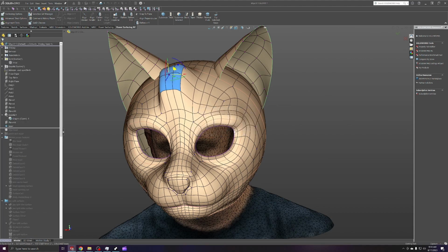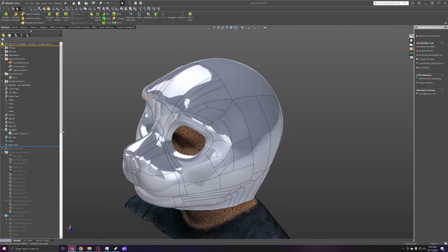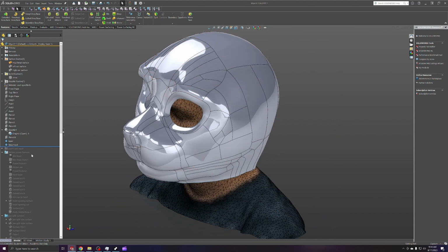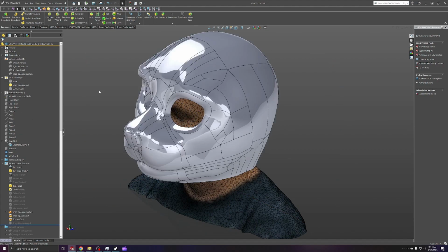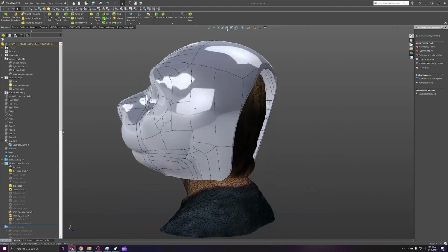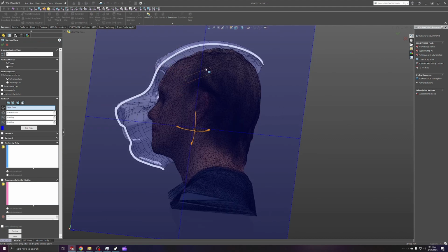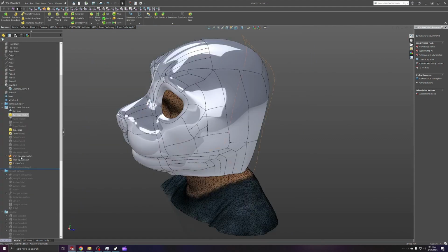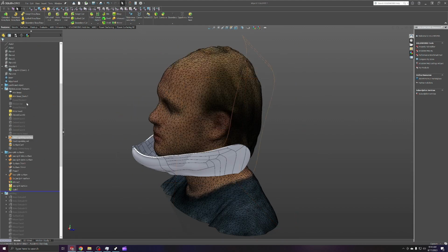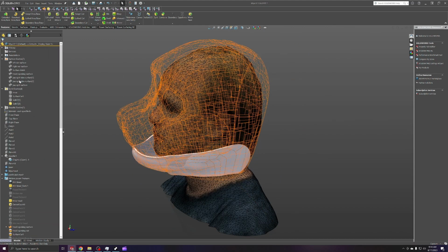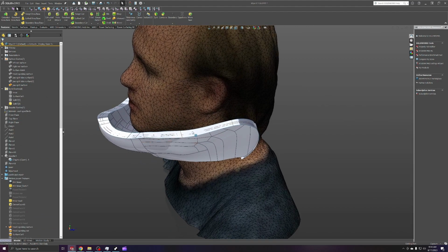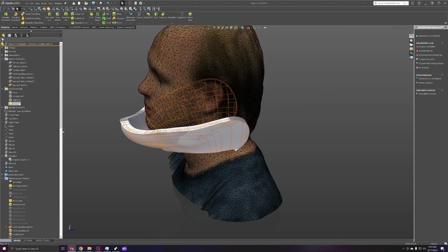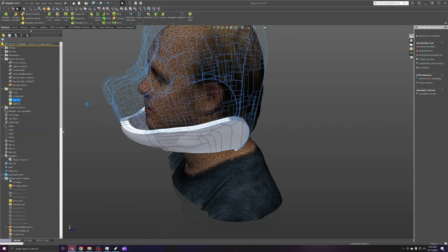So we'll discard changes here, and now you can see that we have this thin surface here. Now if we thicken everything, you can see we have the head and it's thickened. If we take a cross section, you can see it's about that thick. The next thing we do is split this part into multiple pieces. You can see that we have this very nice surface here, which cuts the moving jaw out. So we have the jaw and we have the head.